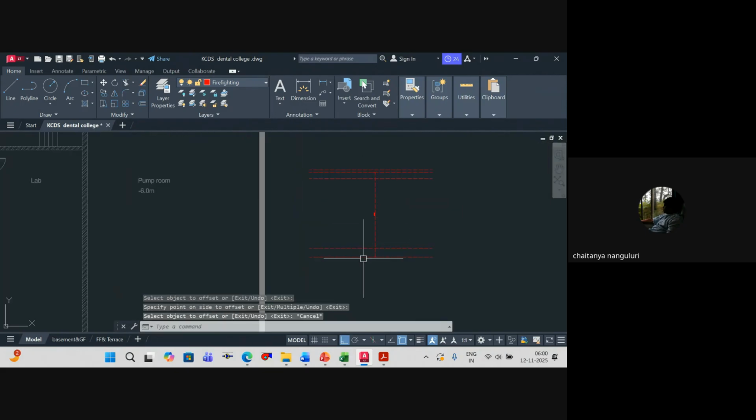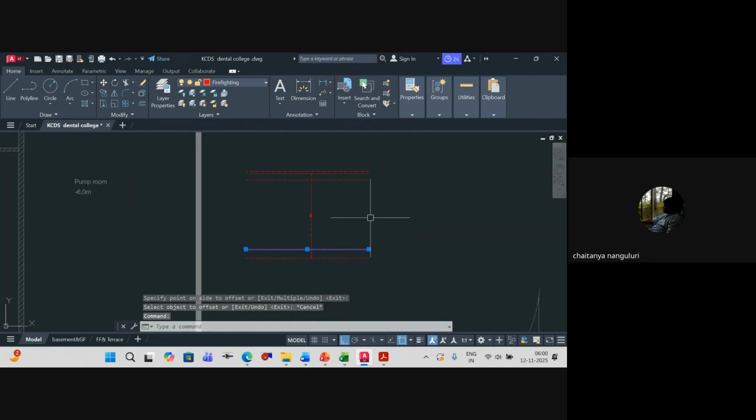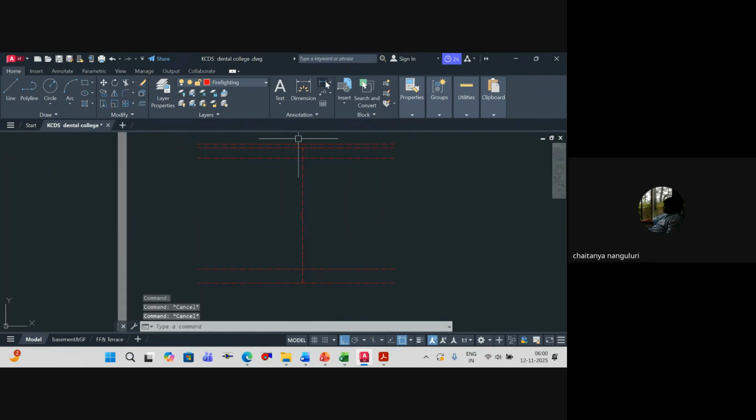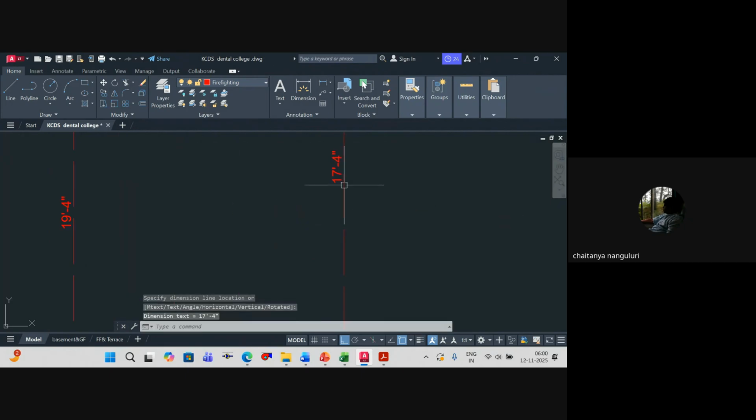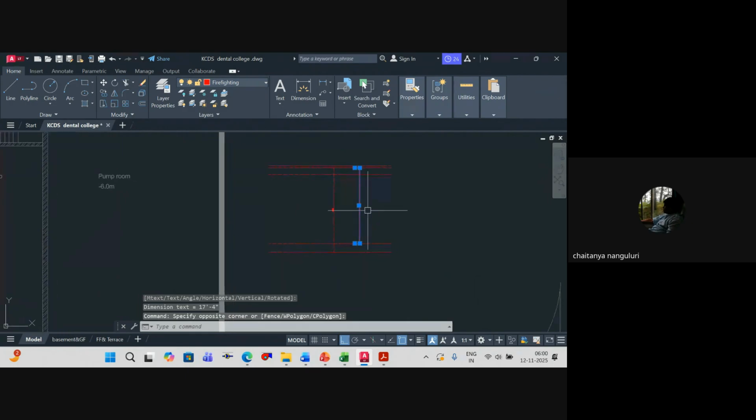So this is the pump floor. This is the flooring of your tank. So the effective height, if you see, is hardly around 17 feet 4 inches. In that again, around 500 mm, we leave it as a freeboard. That means we don't want water to be till the brim. Obviously, we'll not connect it, right? So we will have some 600 mm, around half meter, 0.5 meters, we'll keep it as freeboard.